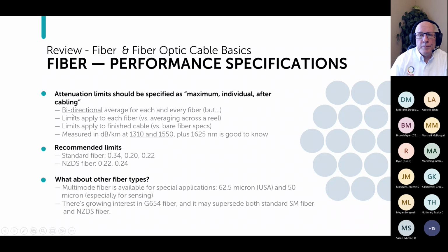First, the limits should apply to each and every fiber. That's what I mean by individual here. Maximum, I think, is somewhat self-explanatory. The loss should not be any higher than whatever limit you've set. So individual is each and every fiber as opposed to averaging across a reel.